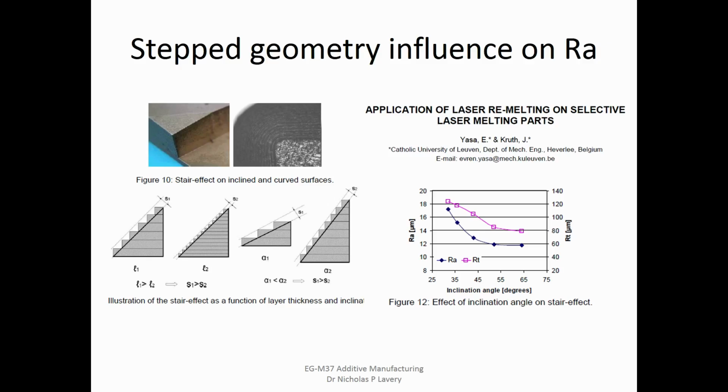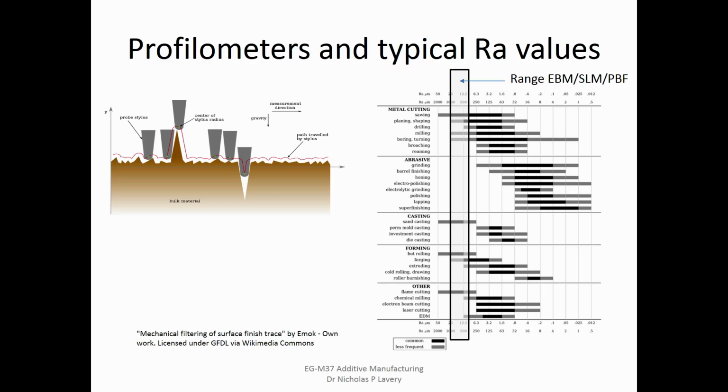So, yeah, I have a question from two slides ago. There's grinding and there's milling. I'm just wondering, if you had three types of post-processes, grinding, milling and sandblasting, which one would you expect to give the roughest surface finish? Probably the milling. I would think, yeah. And the finest would be grinding? Yeah, sandblasting would be second.